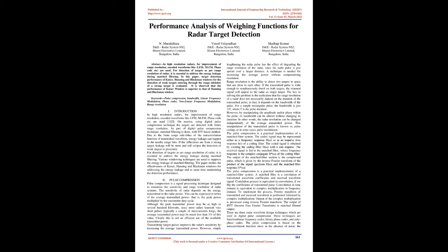For detection of targets as per range resolution of radar, it is essential to address the energy leakage during matched filtering. Various windowing techniques are used to suppress the energy leakage of matched filtering. The paper studies the effectiveness of Kaiser, Hanning, and Blackman windows for addressing the energy leakage and at the same time maintaining the detection performance.